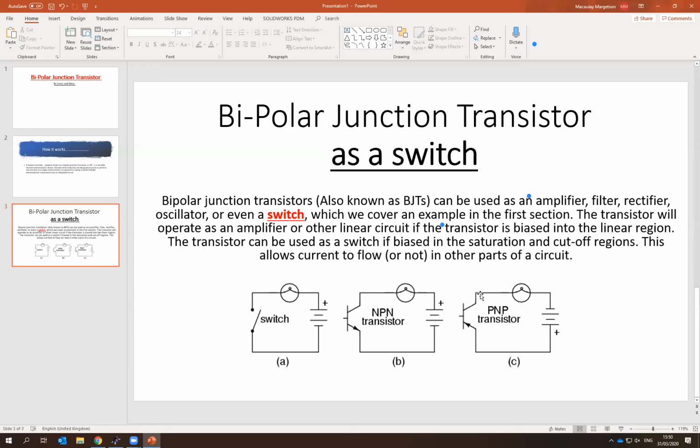What the idea here is, as a transistor as a switch, is we could have a small signal on the base here, let's say half a volt, millivolts, and use that transistor to turn on a much higher current that will flow through this lamp from this battery here. So using low voltage signals to switch higher voltage signals is a use of a transistor as a switch. Also, they can switch much faster than a relay.